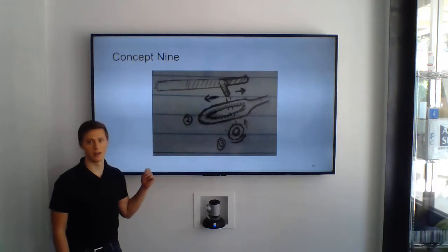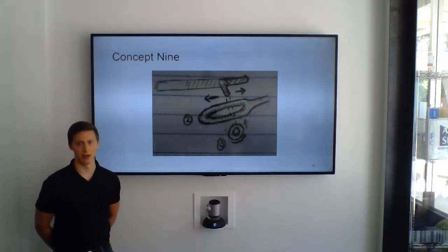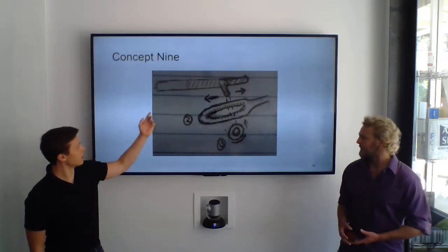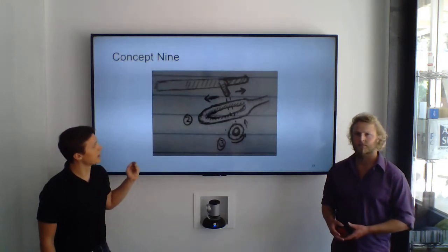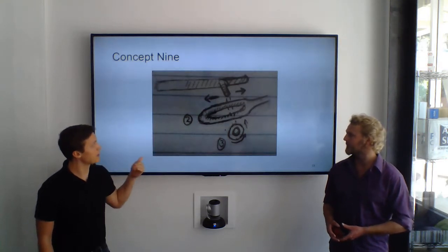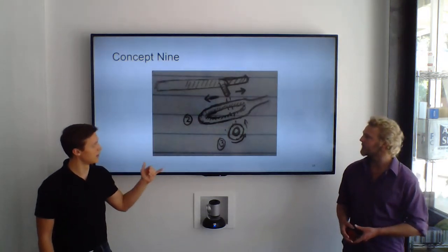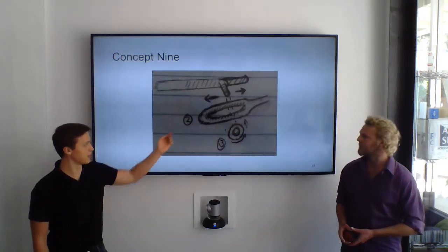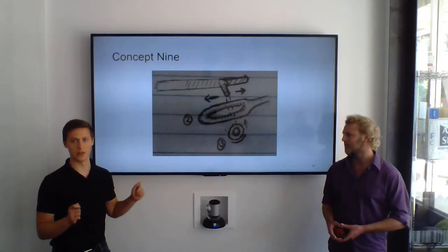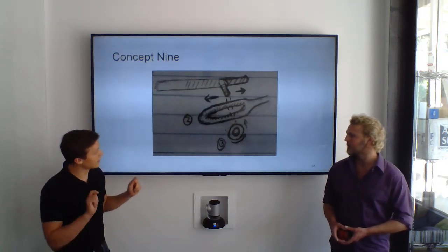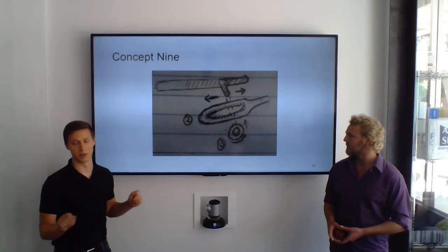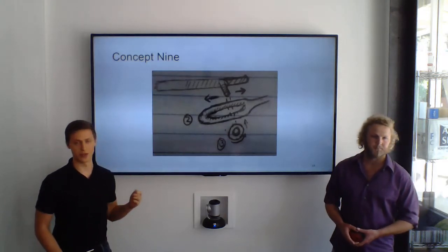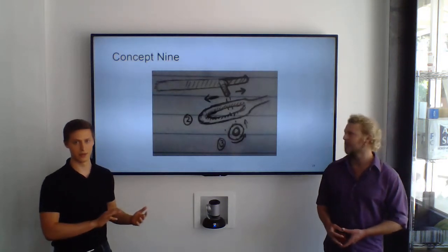So concepts number 9 and 10 both deal with different ways to bind the outer pieces of the kayak shell together. For concept number 9, here you can see one of the outside vertical pieces. This piece has a screw extruding inward out from the piece, along with 2 horizontal guides that run along the top and bottom. This screw and these guides then meet up with the centerpiece, which has a large slot that allows the kayak to be adjustable to a user. Both sides of this slot are coated with a rubberized surface to prevent sliding. Then a hand-screwed bolt is attached to the screw to bind both of the pieces together.